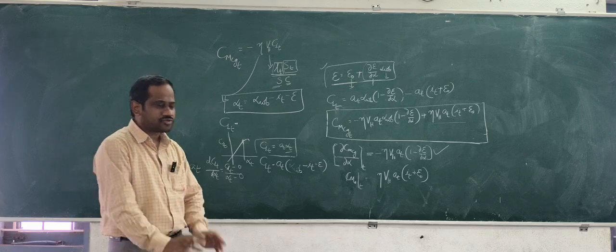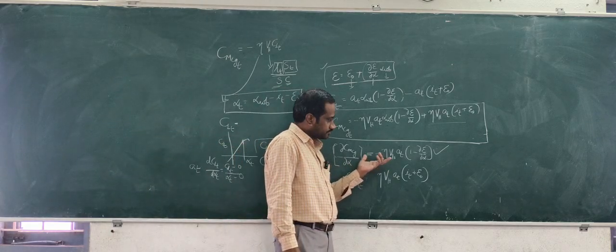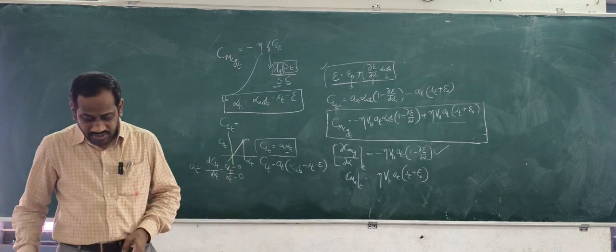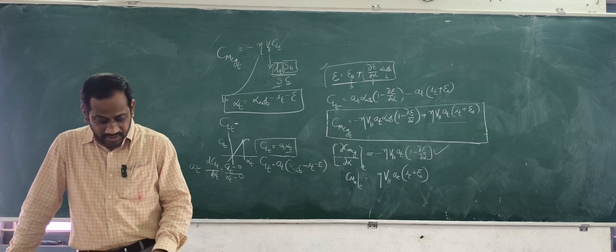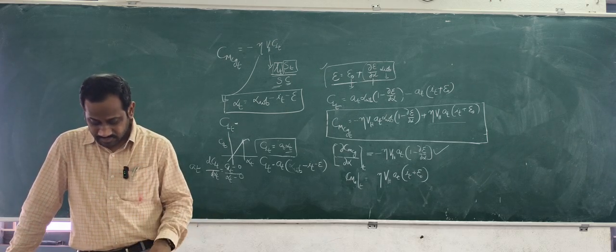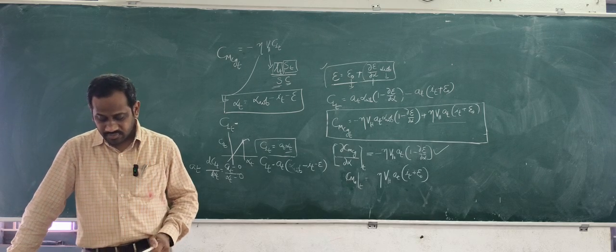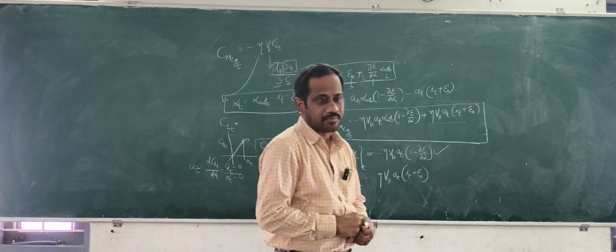So all the parameters should be looked into. Now look at here. So these two things, please write down. The tail contribution CM naught T. Next point. The tail contribution CM naught T can be used to ensure CM naught for the complete aeroplane is positive.